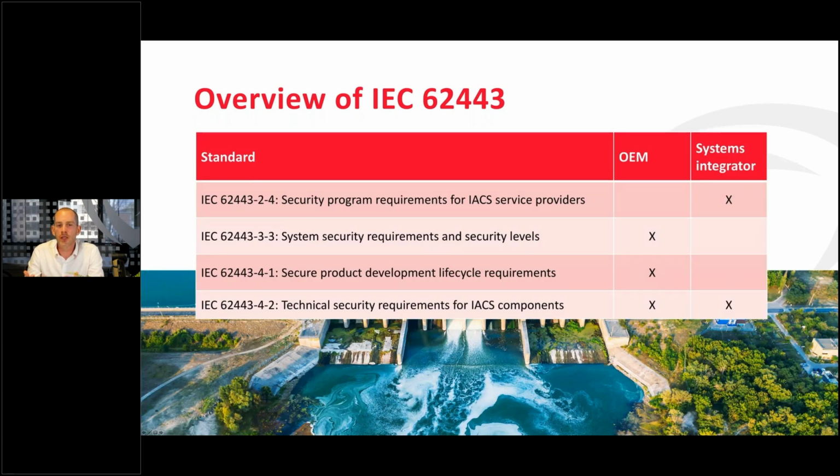As you can see here, in the spread of responsibility between the original equipment manufacturers and the system integrators, there's a good amount of common sense. For example, only OEMs can implement a proper software development lifecycle to rule how components will be developed. Only the OEMs can define how these components will actually interact with one another to form a complete IACS. And then the responsibility of system integrators is especially important when it comes to defining the proper set of rules, the proper set of policies according to which they will be deployed, as well as conducting the proper testing of the security requirements.